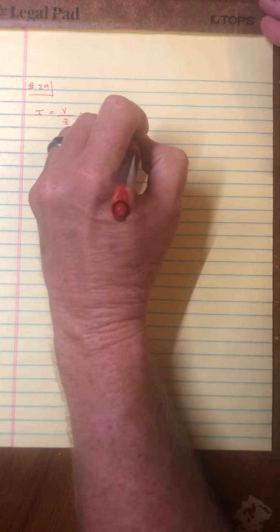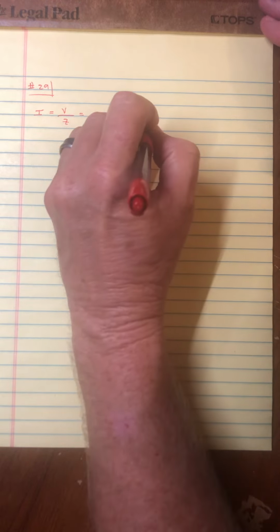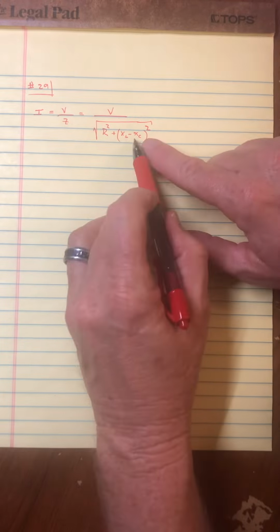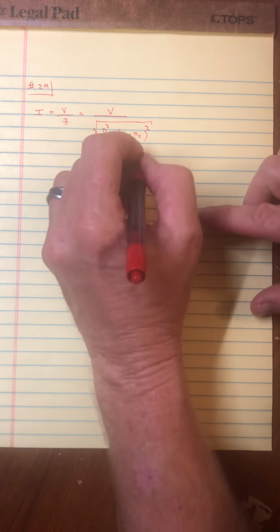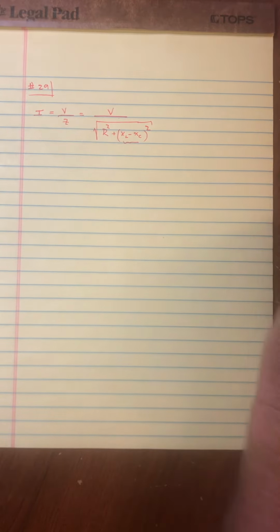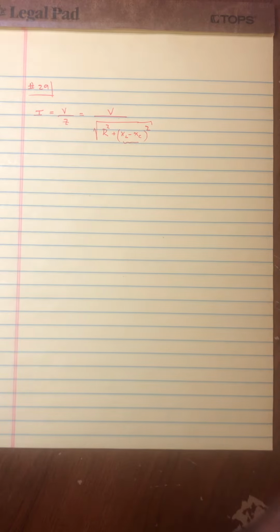So, in other words, the one equation, which you've been seeing throughout this video, is that the current is equal to the voltage over the impedance. And in this case, the impedance includes a resistor, and so let me think of this as one unknown. This is the total reactance, the combination of the inductor and the capacitor.